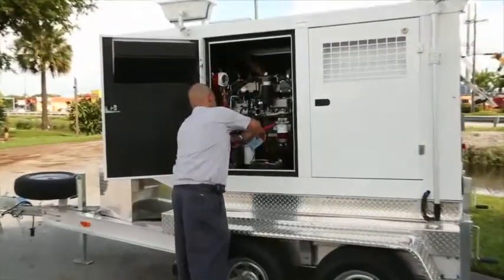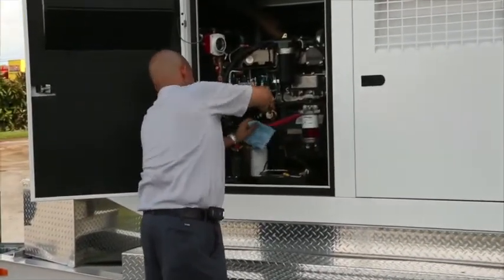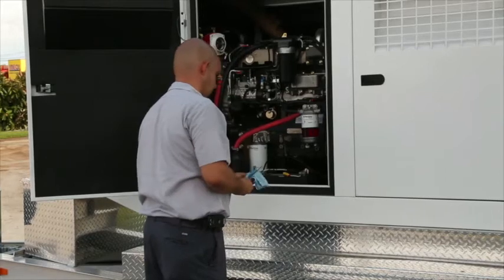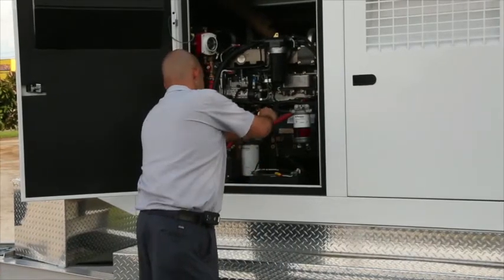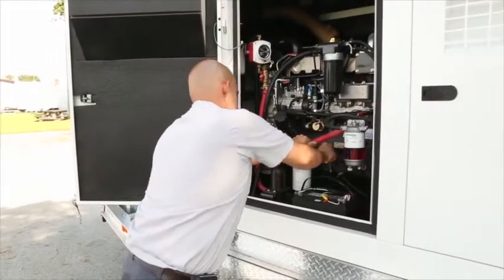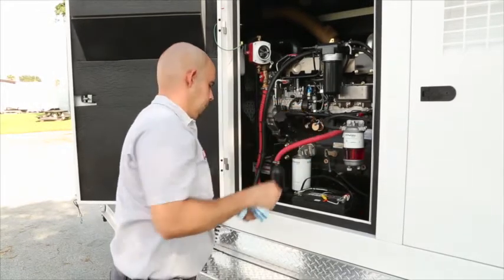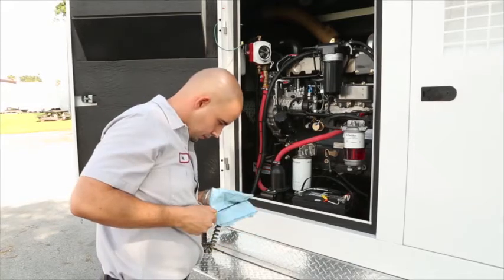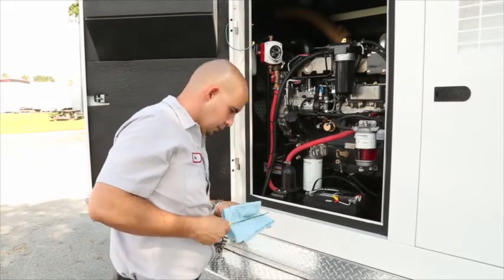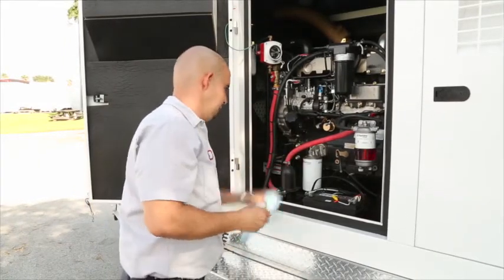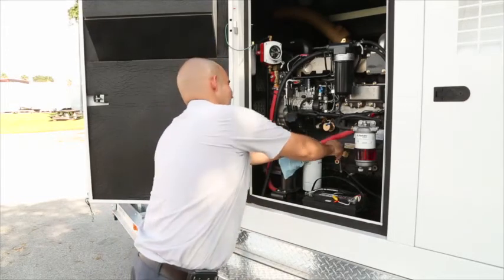Having verified that fueling was not the cause of failure, the operator should proceed to check the other most common cause of failure, oil pressure. The oil level is checked by first removing the oil stick to wipe it clean, then reinserting it and removing it to visually check the oil level to determine if the set failed to start or shut down because of low oil pressure due to insufficient oil.